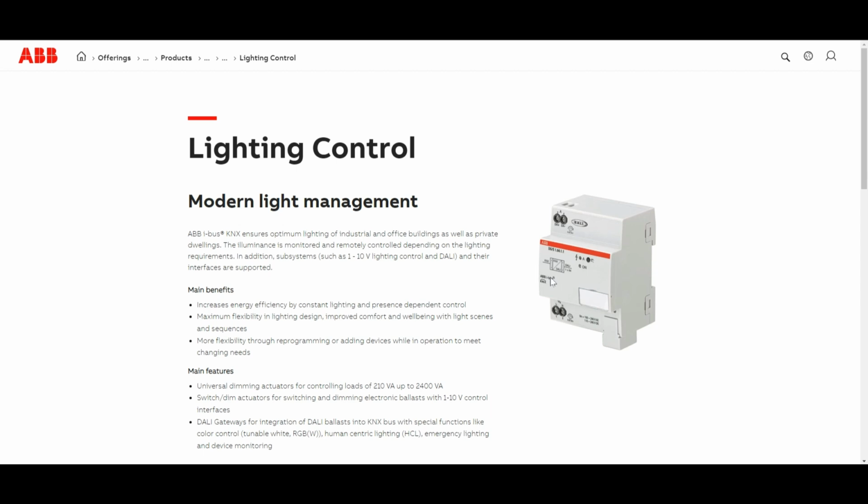What's more important though is it has a feature inside the gateway which allows, without any programming, your installers, being the electricians, to plug straight into the DALI, put power to it, and the gateway will auto address fittings. Once it has auto addressed the fittings in the first couple of minutes of startup with it flashing, it's able to control those fittings through a broadcast control through a button. And what this means for you as an integrator is much more efficiency. A lot of our time is used finding faults in the DALI network, and you are there pretty much trying to find other people's faults.